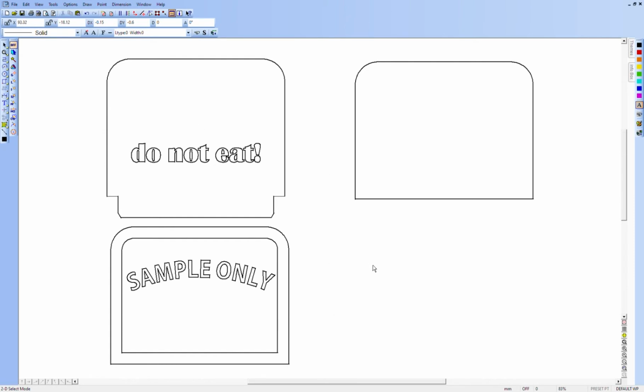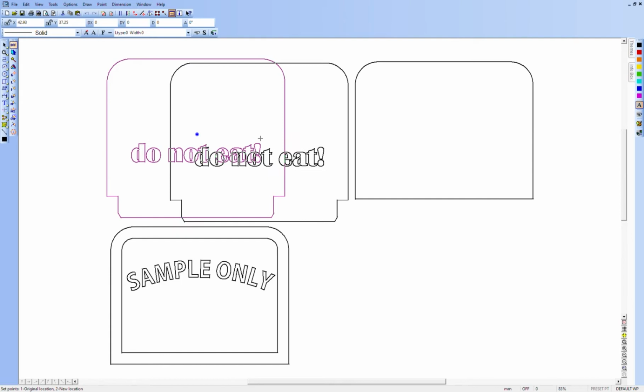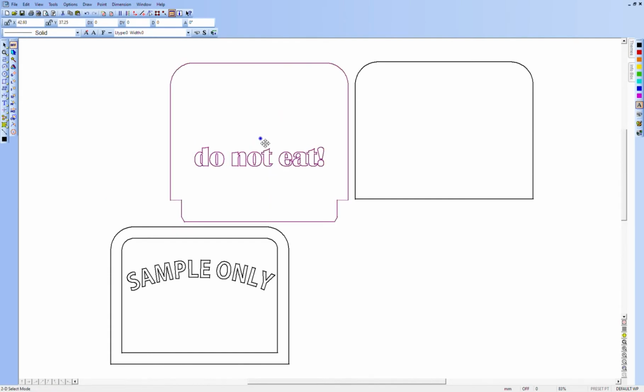If we were to send the file to the laser cutter looking like this, the laser would go around each part completely independently, leaving thin strips of uncut wood between them. But if we look at the right side of the middle piece and the left side of the back piece, those 2 lines are actually identical, giving us an opportunity to save a little bit of laser time and a little bit of wood. If we put these together and only cut the line once, that single cut will form those edges for both of the parts.